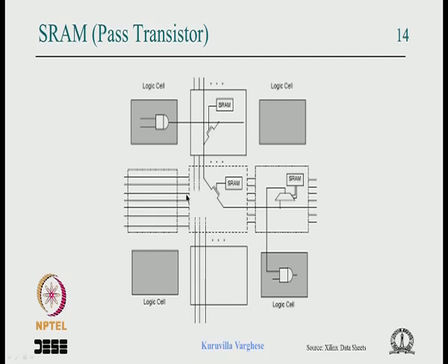So if you assume, say, here it is shown 7 wires. So if it is 7 into 4, 28 wires, even if one wire is connected to 3, you can say 28 C2 kind of connections are available for it to connect to everything else. So it's quite a lot, 28 into 27 by 2 connections may be there. So that involves a lot of transistors, into 6. So these switches occupy quite a lot of area.